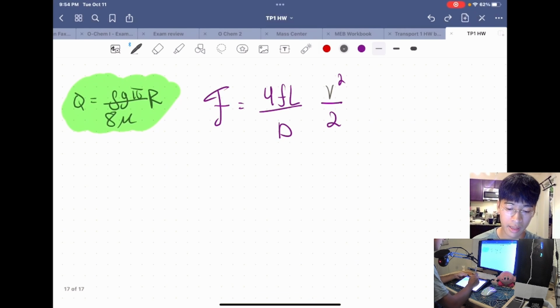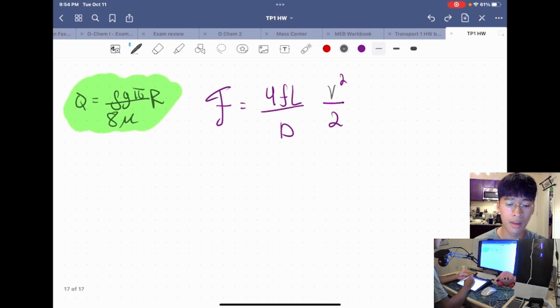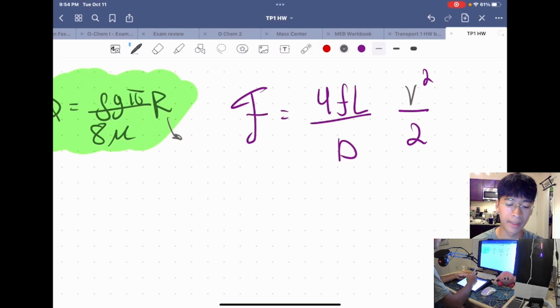And we have this 4 and this 2 here, and you might be tempted to go off and simplify that. And true, there's nothing wrong with doing that, but the motive behind expressing frictional heating like this is that this is extremely similar to our velocity term in the Bernoulli's equation, right? That's why it's being represented that way. So the point being is that this is diameter and this is radius. So we would like to turn this into diameter because the pathway to do that is extremely easy, and this will open up pathways for potential simplification. Okay, so that's the motive behind turning big R to radius.